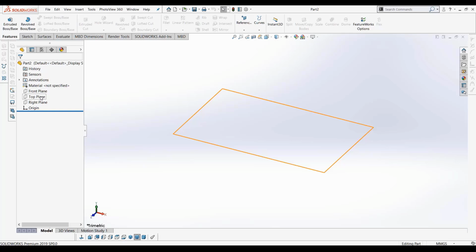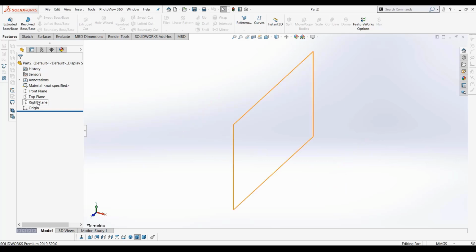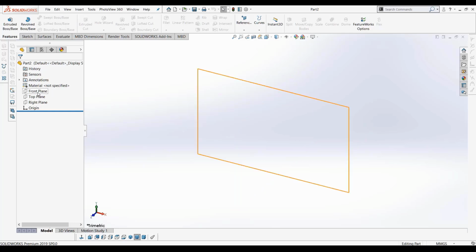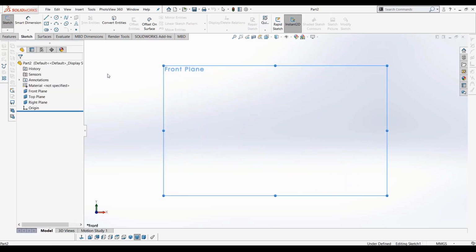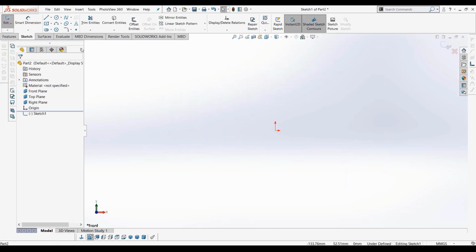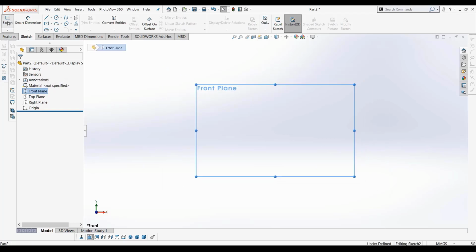It's very important to know from which view to start. I will start from the front view. Let's select the front view. You see why I say we should select it. If we don't select it and try to create a sketch, it will tell you that you must draw the sketch in a plane. In which plane? In which view? You would have to select it again, or choose it from here, and there's a chance you might make a mistake in your selection. So please, let's just follow the same program and use the selection toolbar to create the sketch.